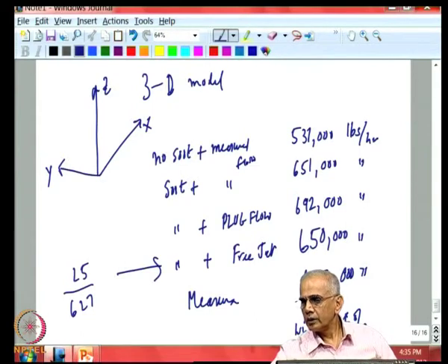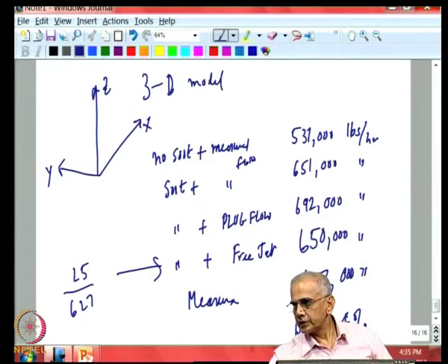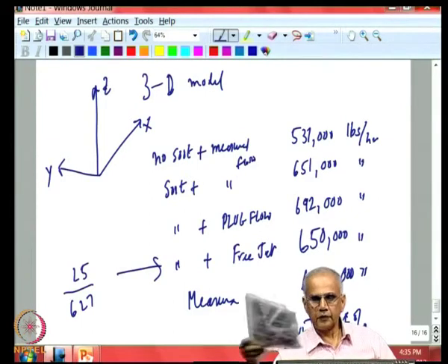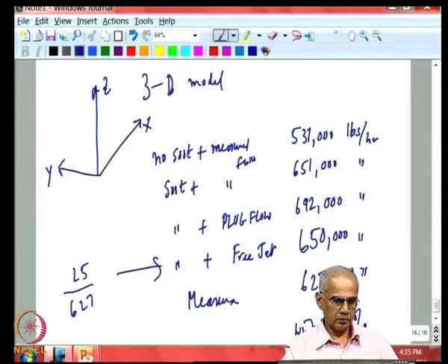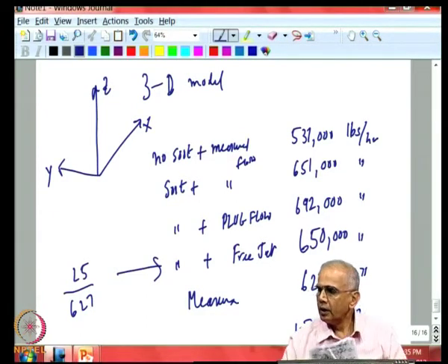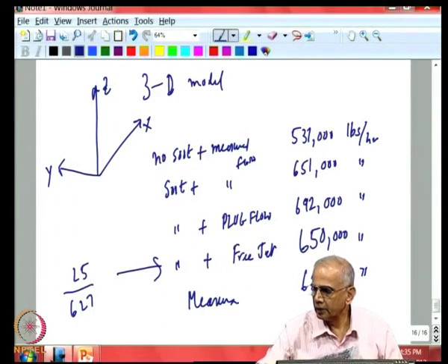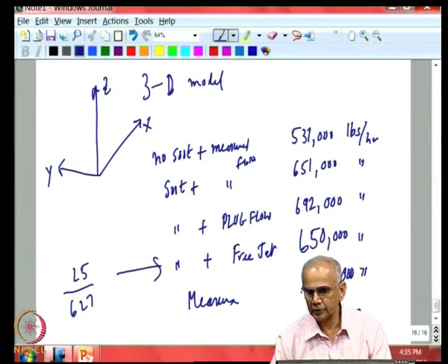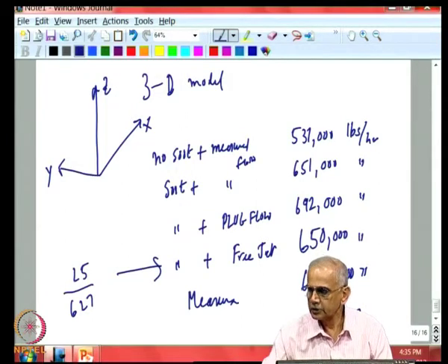And as you pointed out, if you want accurate information about the performance of furnace, you cannot hope to do so with a simple 0 dimensional model. 0 dimensional model serve the purpose of a tutorial. So, finally, the ideas from the 0 dimensional model were utilized in the 3 dimensional model to estimate the steam generated in the boiler to within about 4%.